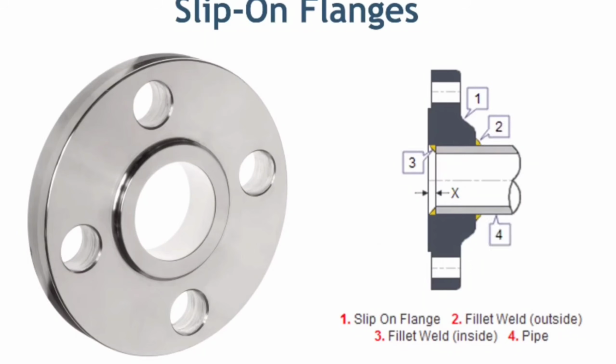The inner bore of the slip-on flange is a little larger than the pipe OD, to make sure the pipe or fitting end can slip into the flange. The slip-on flange is fillet welded with the pipe or fitting and the pipe. No need to do the bevel end, just square end is okay for welding.